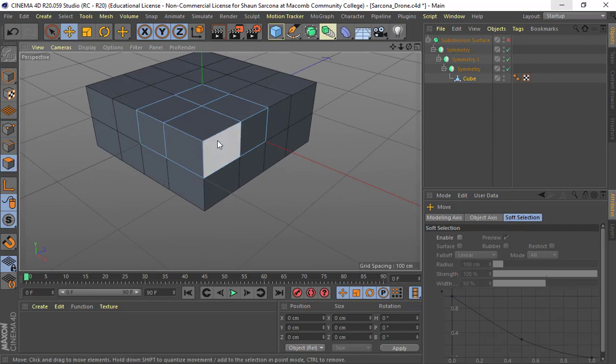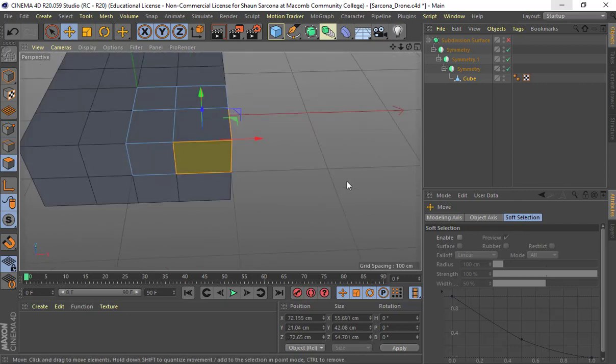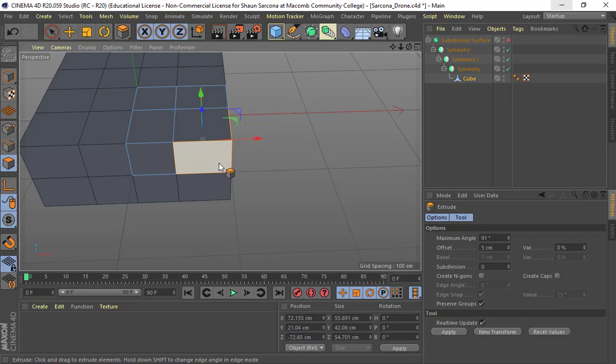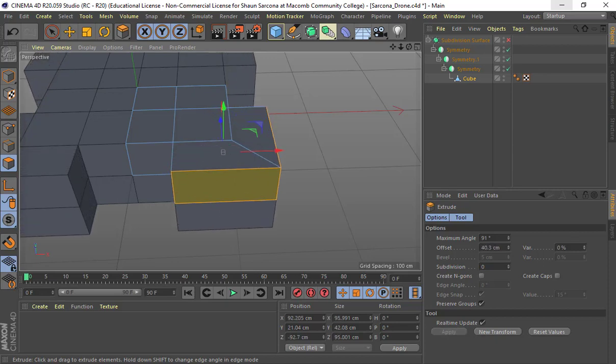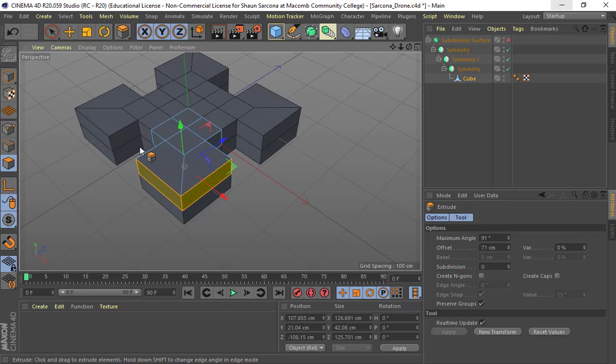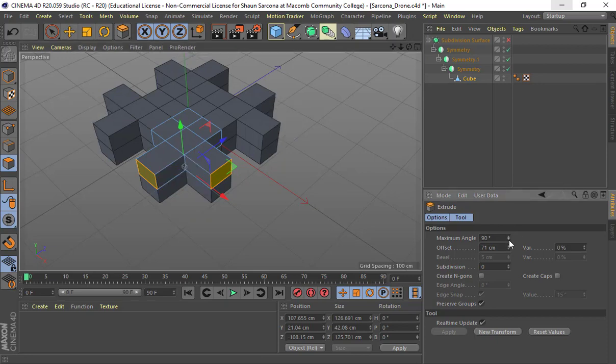So now I can go into this and this, go to my extrude, it's D. I just remember what software I'm in, I just want to verify. Yep, so there's Extrude. It's MT or D. Okay, and then I'm going to pull this out. And you'll see how it pulls out from all four sides at the same time, even the bottom. Now, as I pull this out, typically it's going to do this.